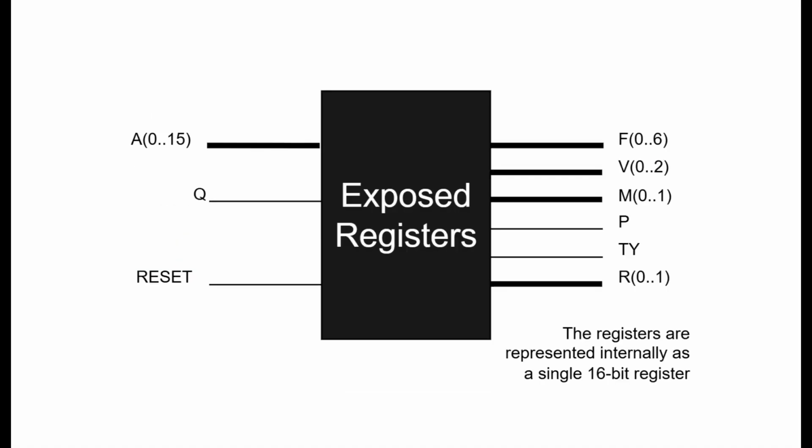Another important feature that keeps turning up is configuration. The SAM maintains a set of internal registers that define how it behaves, but the real trick is that the SAM has no visibility of the data bus. The only way to change the SAM registers is bit by bit, using even addresses to clear a bit and odd addresses to set them.